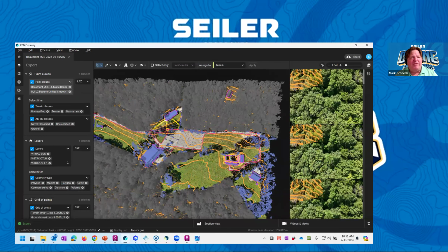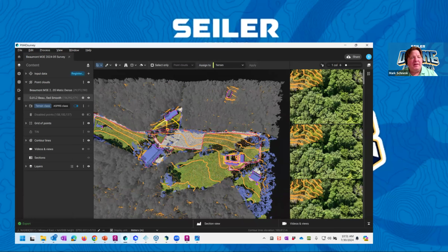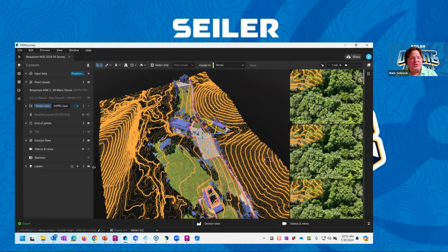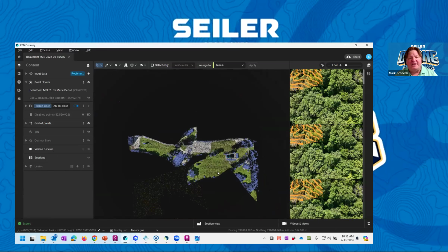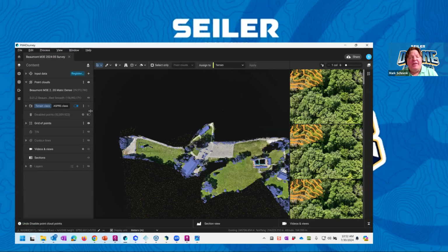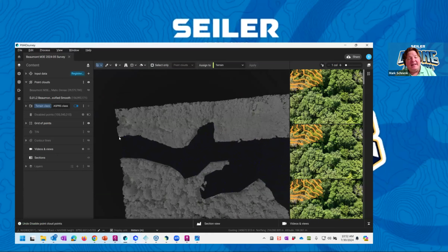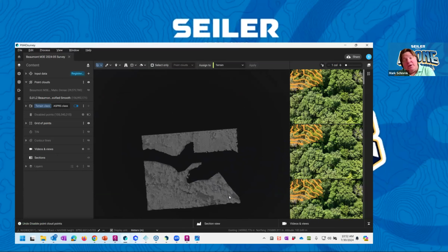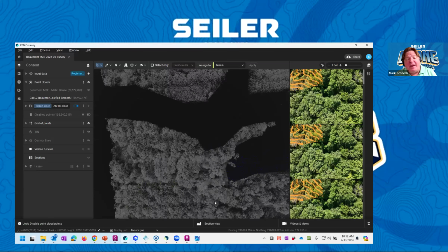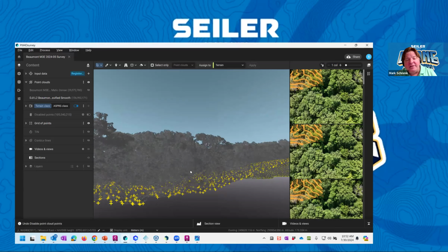So with photogrammetry turned off, go to my layers, with the LiDAR turned off, you can see what I've done. I have turned off those contours and contour lines and grid of points. So I took my full-on photogrammetry and there's a tool in here to select. I just selected a bunch of data here and said, oh, by the way, delete this. Hit delete off my keyboard, and that removed that data out. Right. Then bring it back in. Then I did the opposite. I brought in the LiDAR data, and I trimmed out the same area that the photogrammetry was in, and now I get the added benefit with this type of data here. I get ground data and top surface data.